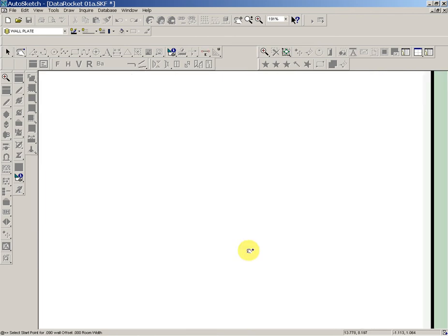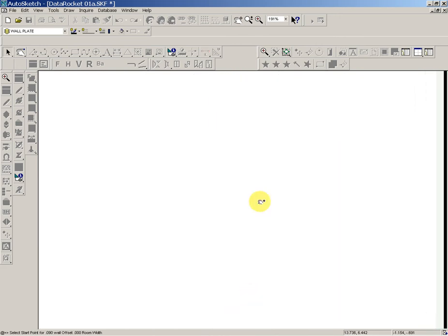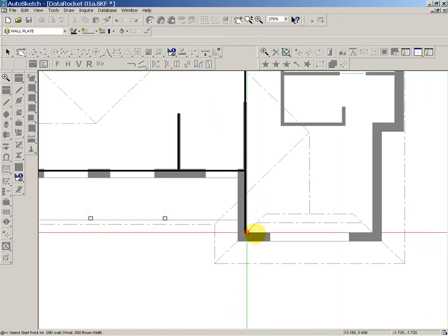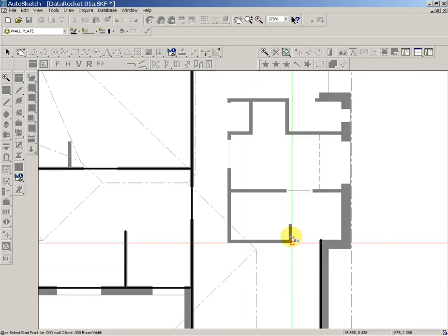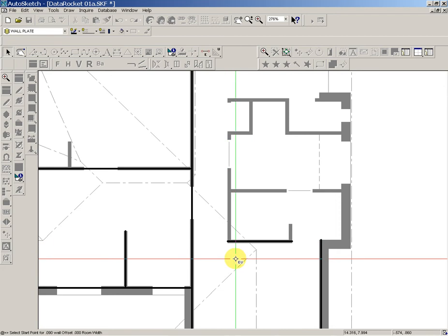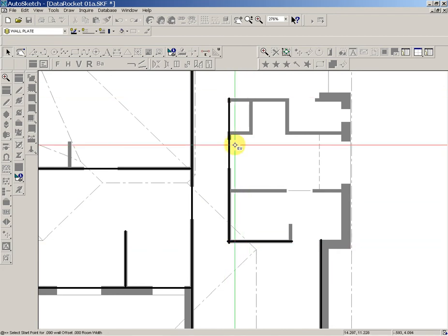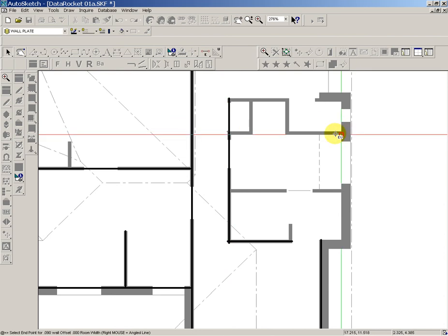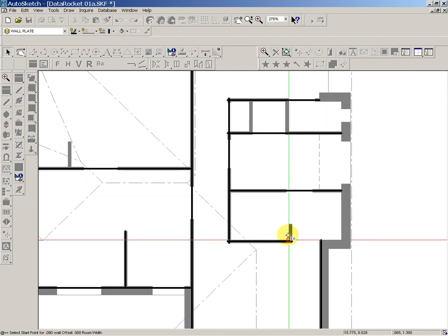In this case here, I'm going to go from the top all the way to the bottom, because with wall plates all we're going to do is total them up and order them as a total length rather than as single items. So we can see here we're going over the top of openings. Now this allows for your waste as well, so just be careful with how you do your waste depending on how you're going to draw your items.